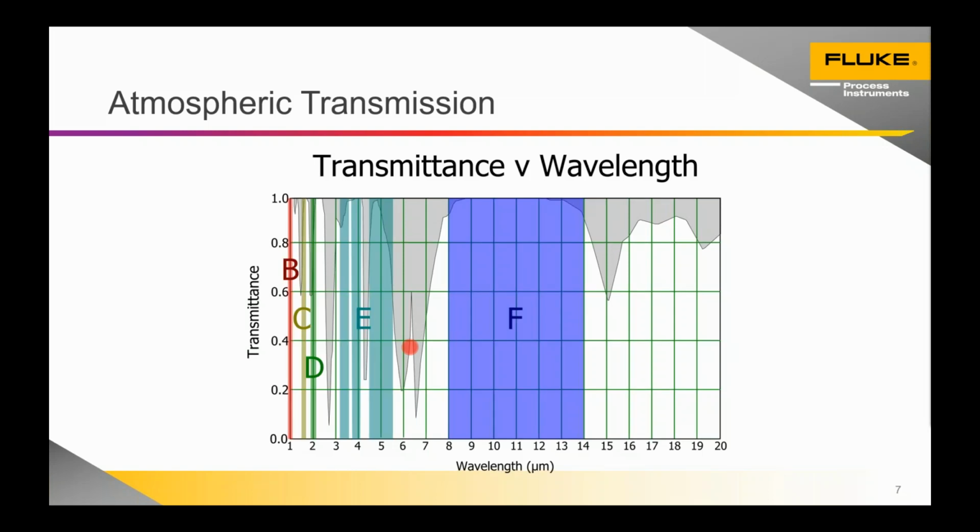And this next slide shows each color band is a typical region where we make sensors where we just have windows to look through. In the case of the biggest area, F, luckily we've got a big window over a broad spectrum that allows us to make devices and everybody else in low temperature. And we also have a window that allows us nicely to measure the temperature of glass here. And then as we move further down, it's windows where we can measure metals and thin plastics.